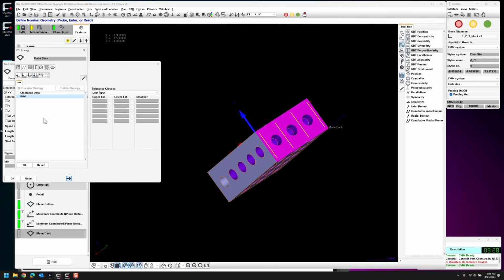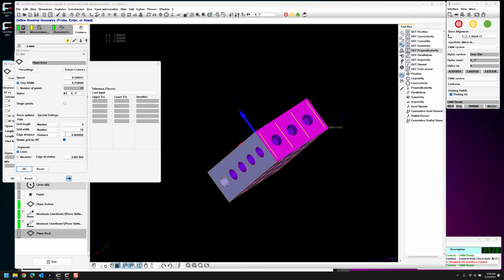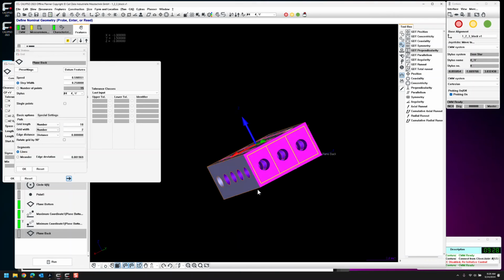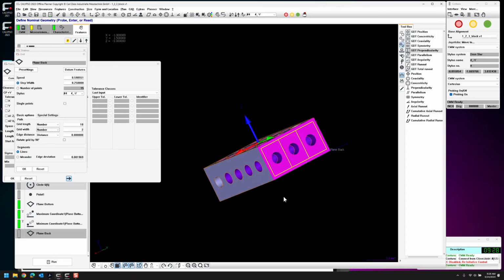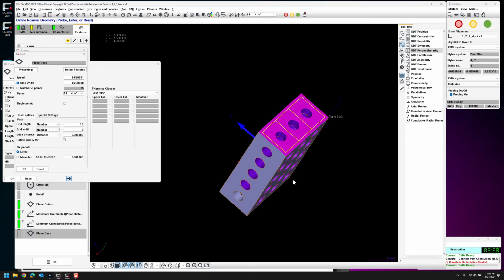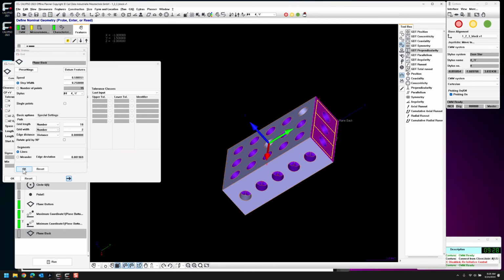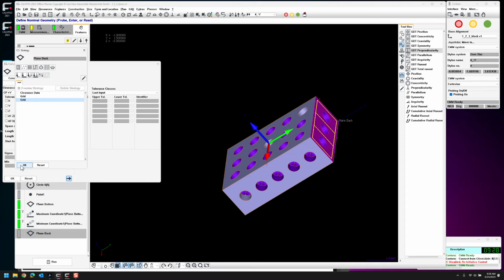And then I'm going to copy paste. I'm going to take the second grid. I'm going to unrotate it. And now my number is going to be 2. And let's leave this back at 10. So now I've created a complete box. It's going to go 4 vertical lines, 2 horizontal lines to give me a nice thorough definition of that surface for the purpose of profile calculation.